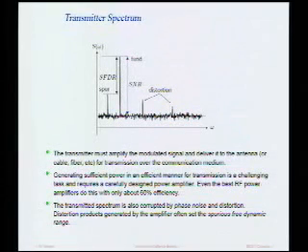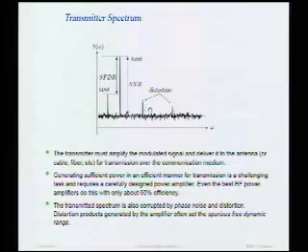They may be in somebody else's channel and now we're causing interference? Exactly. If we want to be good users of the spectrum on the receive side, we have to be good users on the transmit side as well. So we basically want to transmit information in the bandwidth that we've been allocated, and we want to transmit as little junk outside of that bandwidth as possible. In fact, there's usually a spectral mask that we have to satisfy, which is again set by the standard of communication that we're using.